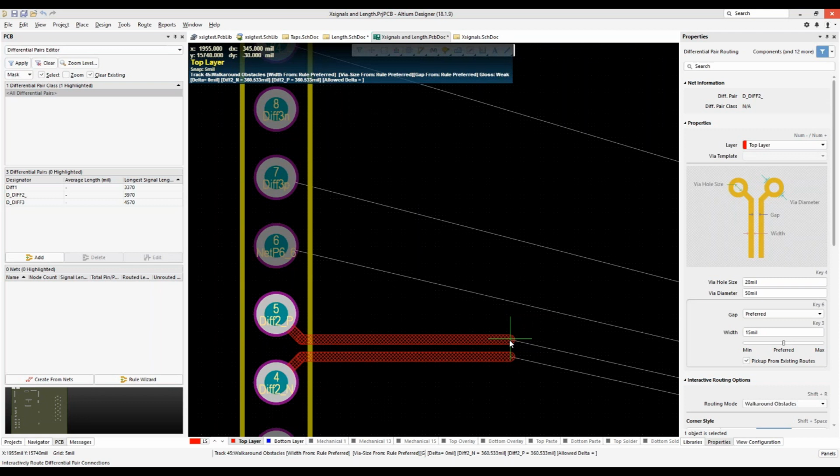And when it goes to the receiver, as long as it meets the setup and hold time, the receiver will declare that to be valid and take it in. If there's noise, the idea is that the noise is going to be equal on both lines. And so when the receiver gets it, it will reject it because it's not equal and opposite.